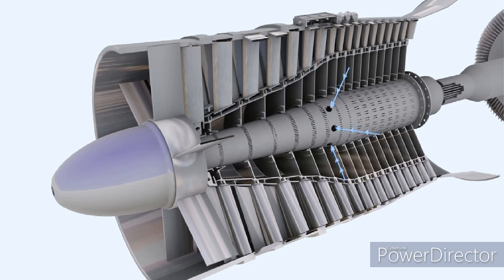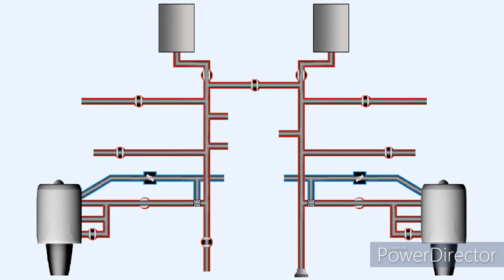The air bled from the compressor, which is used for cooling the internal components of the engine, is also utilized to pressurize seals, which will increase the efficiency of both the compressor and the turbine. Air bled from the engine compressor is also used to service many aircraft systems.